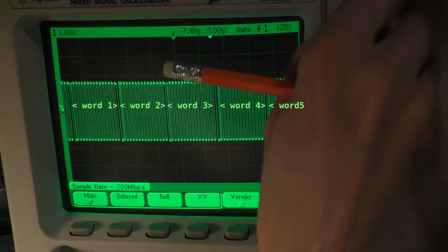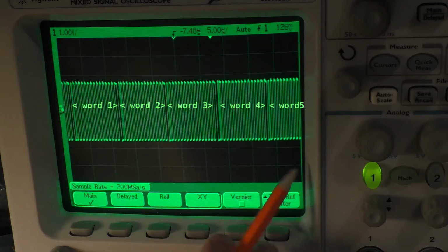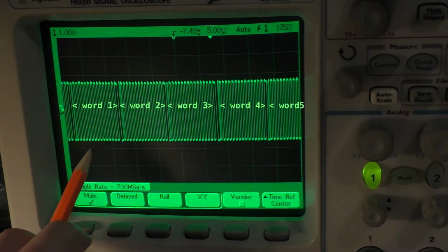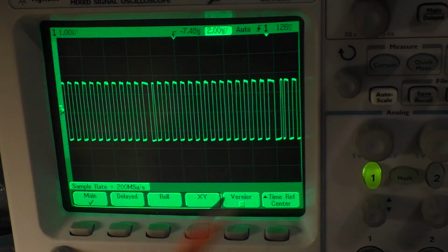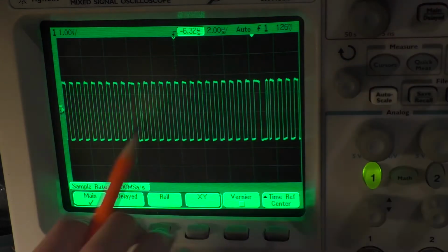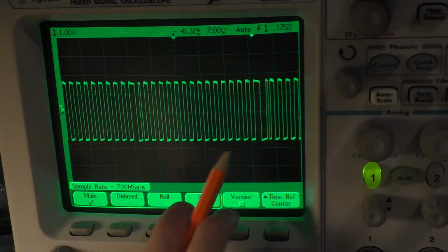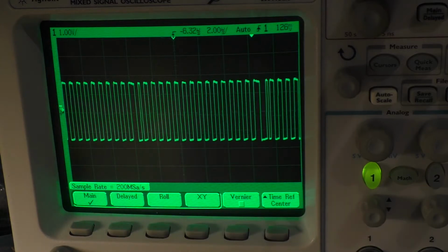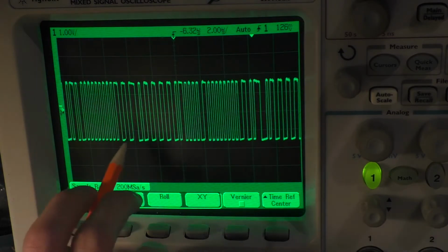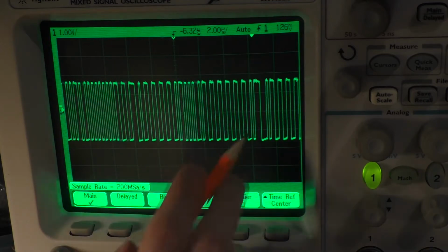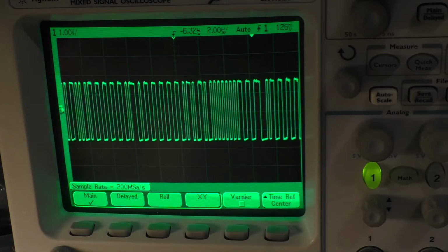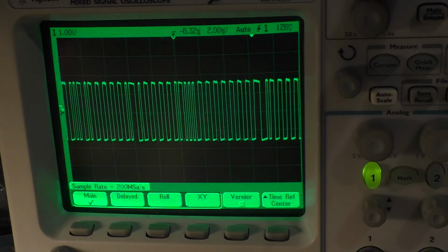You can easily see where each data word is, because now the data words are just full of zeros. So like over here you have a synchronization bit here, and then a bunch of zeros, that's a data word. And if I start playing something, then you can see that suddenly these ones are starting to appear in the data area.